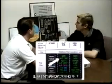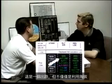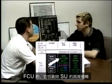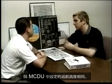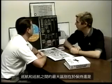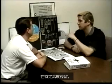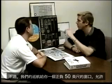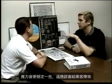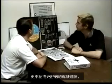What about ALT CRZ then? Well, ALT CRZ is basically the same thing. It's an altitude hold, but instead of just engaging the altitude at the FCU, it's going to be engaging an altitude that's in the FCU as well as the cruise altitude set in the MCDU. Big difference between ALT CRZ and ALT, though, is ALT is a hold at a specific altitude. ALT CRZ, though, gives you a plus or minus 50-foot window that allows the thrust to be a little more stable, which supposedly gives the passengers a smoother, more comfortable ride.